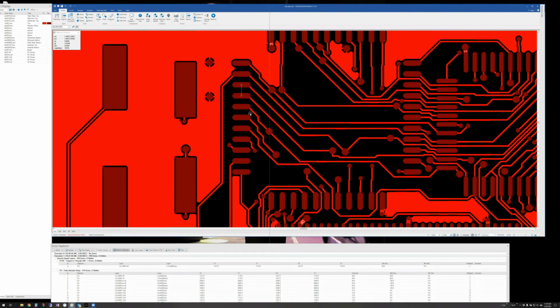Now, you may want to make your scan box bigger to make sure that you get the center of an object. So I did that with the page up button, and again, this is in the help, but as you can see, when I do that, I get the same measurement, but the page up and page down increase the size of your scan box when you're doing this. So you may find that useful.